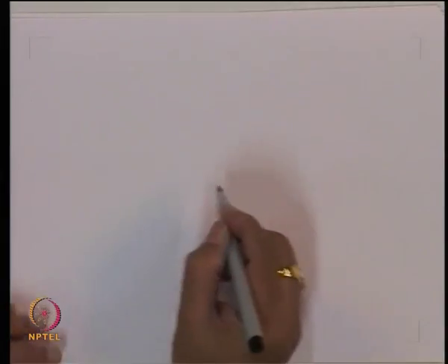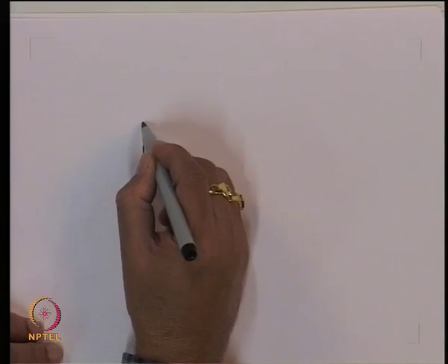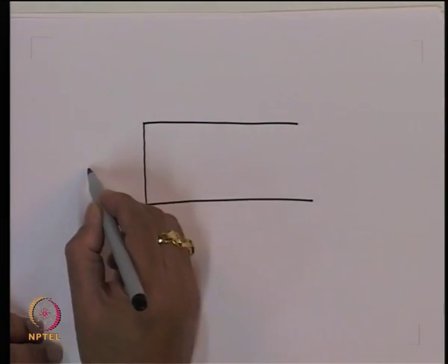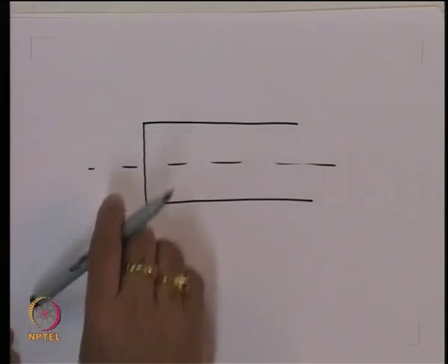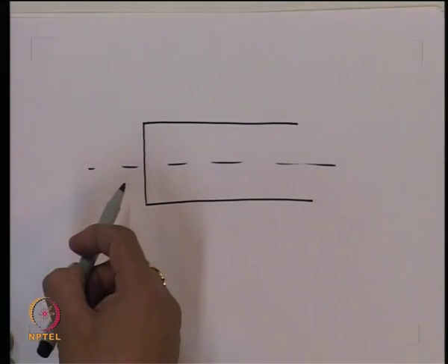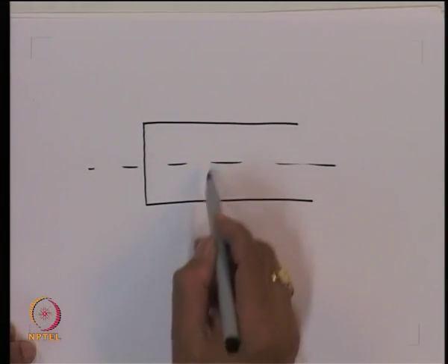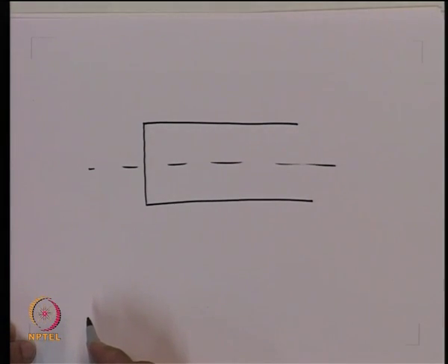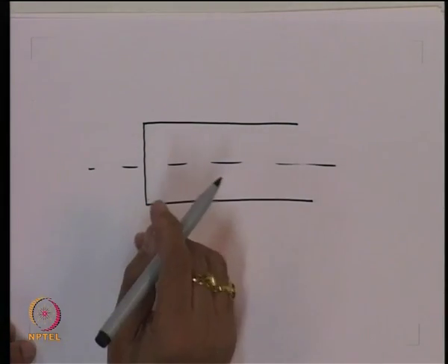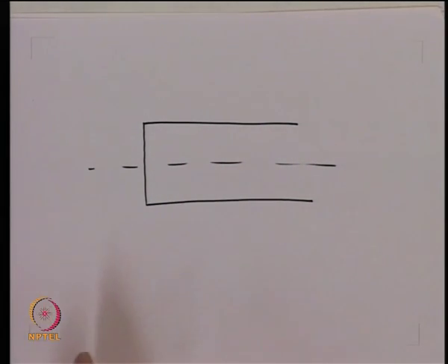Compare this now with the skew rays which are going at a certain angle with respect to this meridional plane. So, if I consider, let us say, an optical fiber like this, and the ray goes at an angle which is not in this plane, but is something like this. If that happens, as we have seen, this ray essentially spirals around the axis of the optical fiber, and as a result you can show that in no circumstance will you have a configuration which is purely transverse electric in nature or purely transverse magnetic in nature.